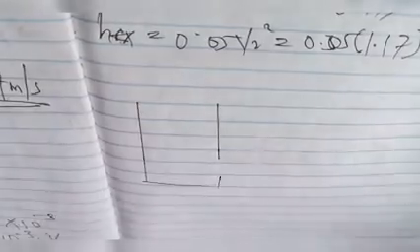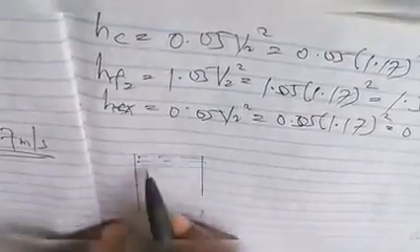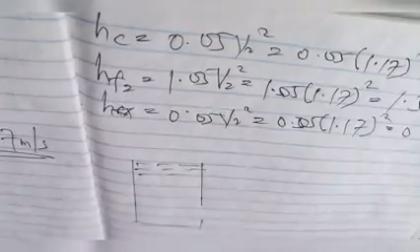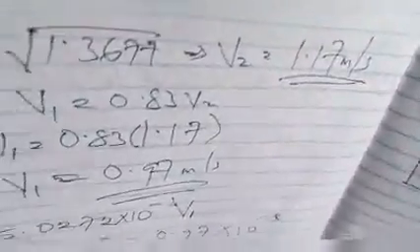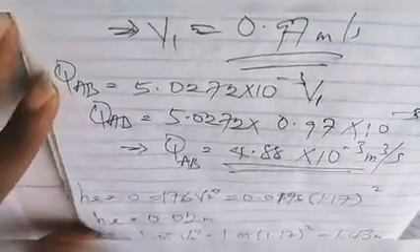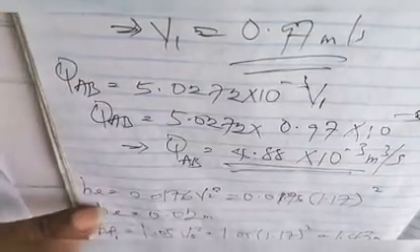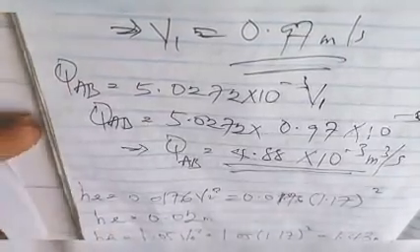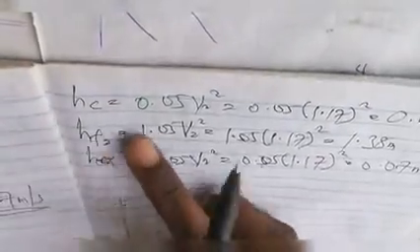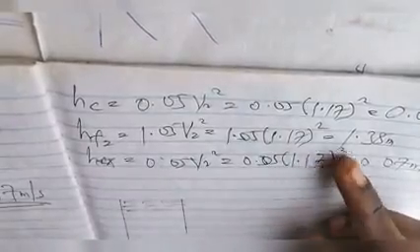We want to draw the energy gradient line first. First thing to do, from the liquid level, you measure out the head loss due to entrance, which we obtained to be 0.02, and every other head loss we have here: 1.43 friction at pipe 1, then 0.07, then 1.38.